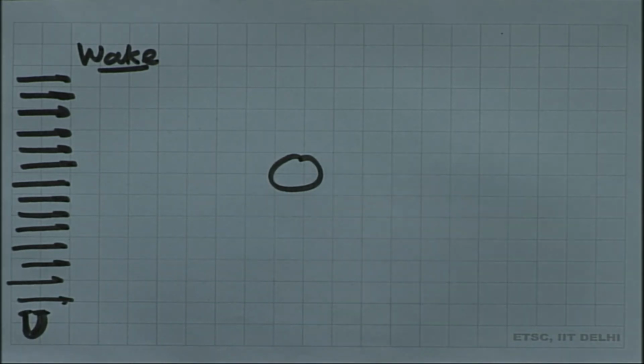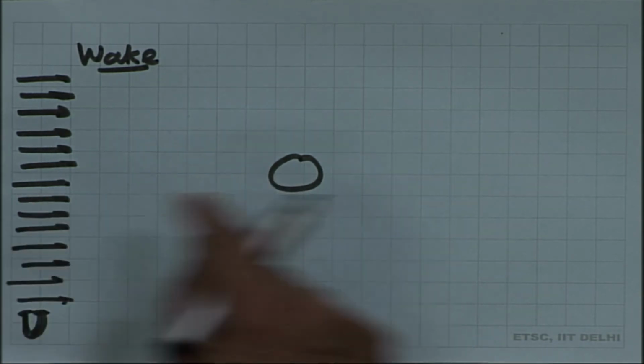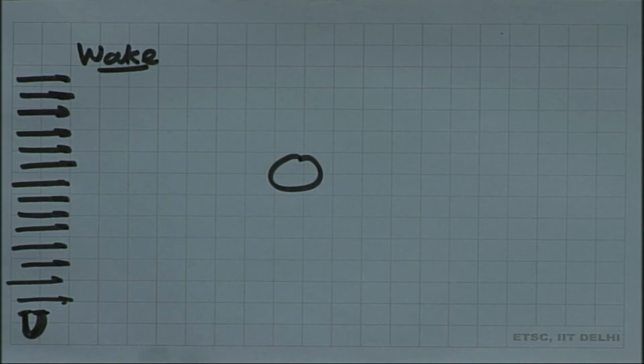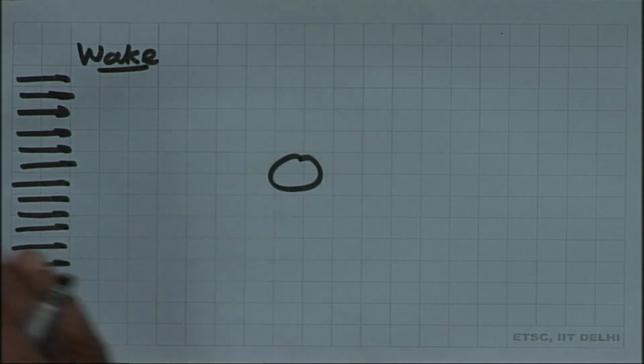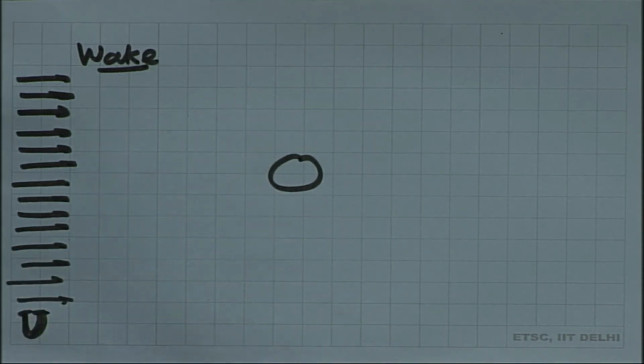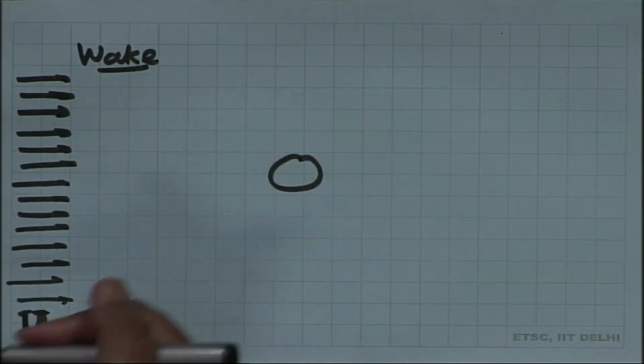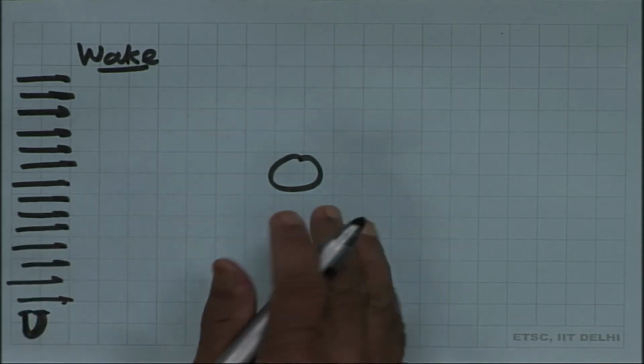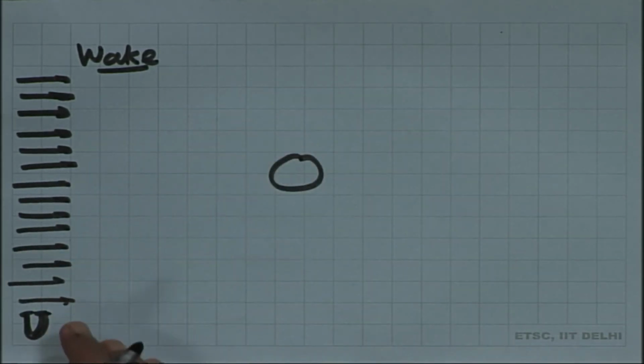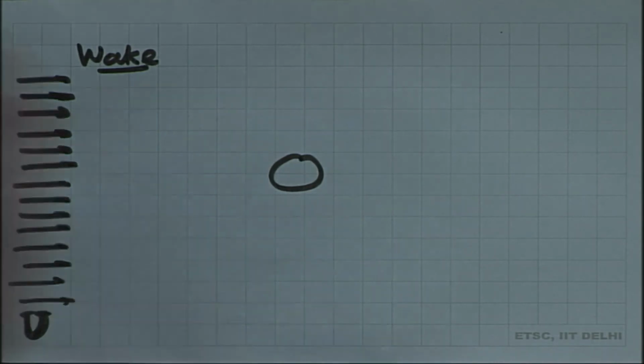Actually, this is nothing but if a plane is flying in still air and the plane is moving to the left with a velocity U, this is the same problem, but we have just changed the reference frame. If we fix it on the cylinder which is moving with capital U to the left, and I sit on that frame, then I will see this is the reference frame for a still cylinder. So, this is what we have, flow past a cylinder.